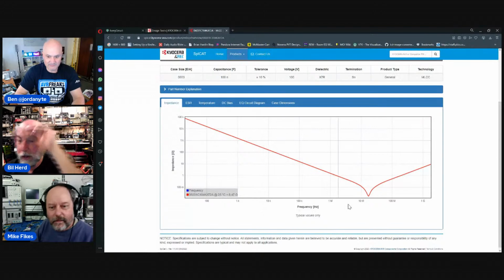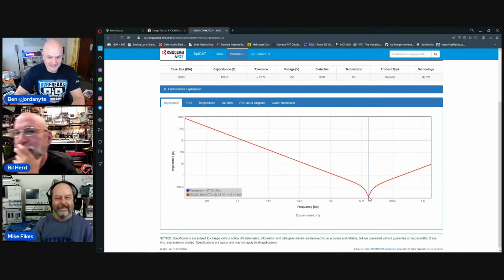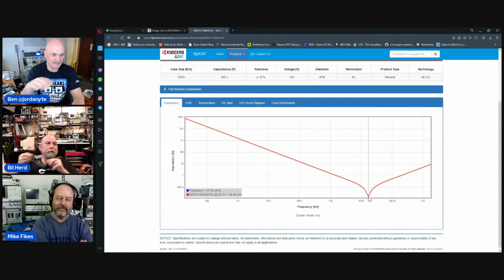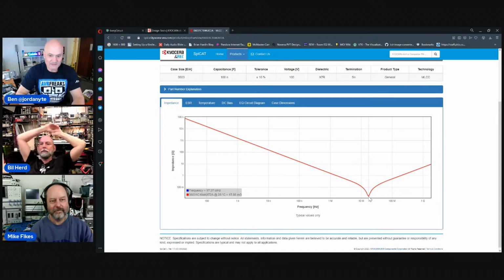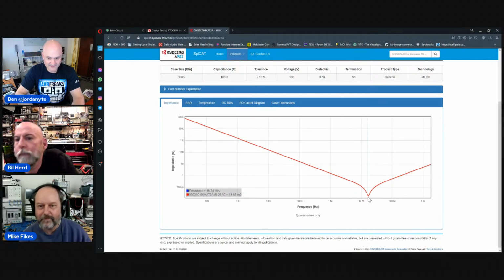That one's a 4262A, but yeah. And when you're ready to share it, I don't know why, but clicking it off the tab and back to the impedance tab shows the impedance again. It's working this time. People, this is based on measuring the actual parts off the production line and creating a stochastically accurate model. The minimum impedance of your typical 0603 100 nanofarad decoupling cap with X7R temperature coefficient material is at what frequency? It's 16, 17 megahertz. They're really, really good to 17 megahertz.